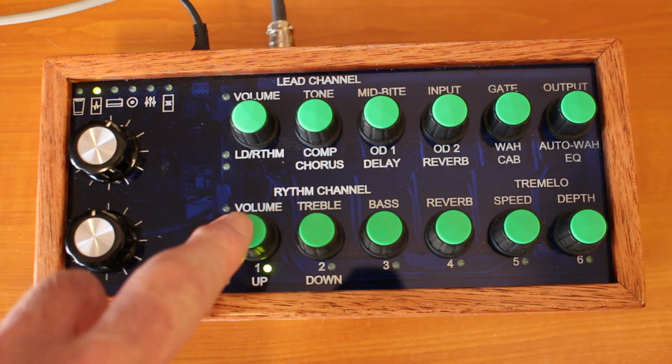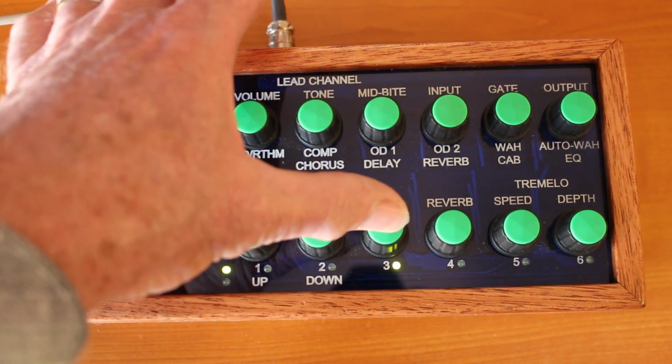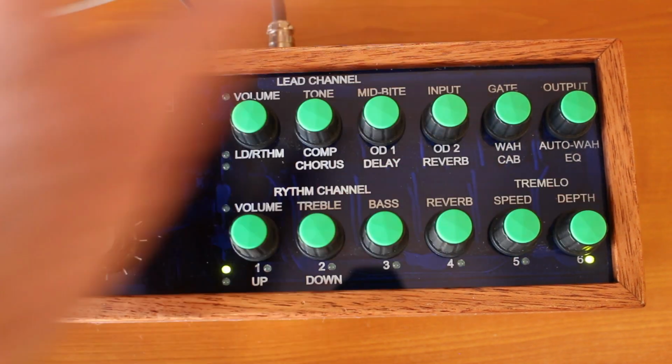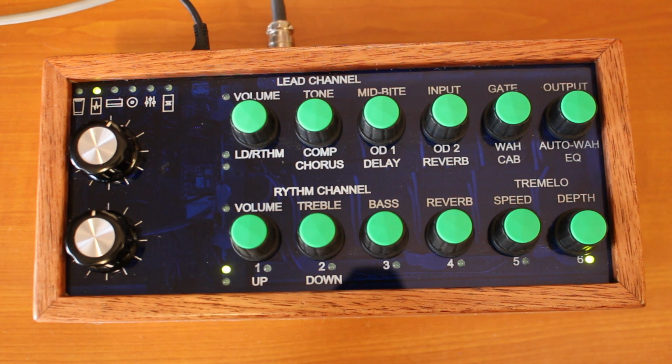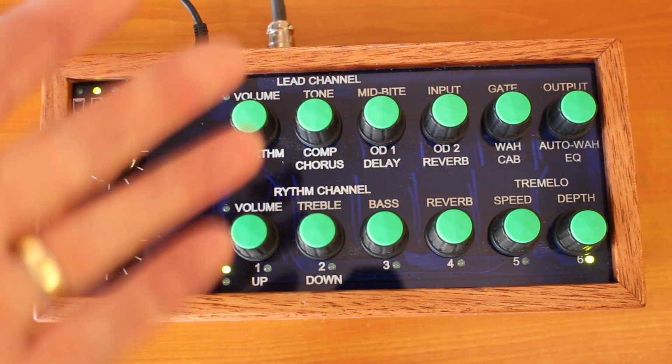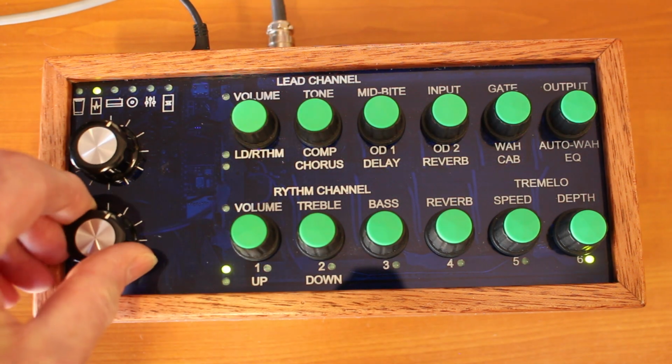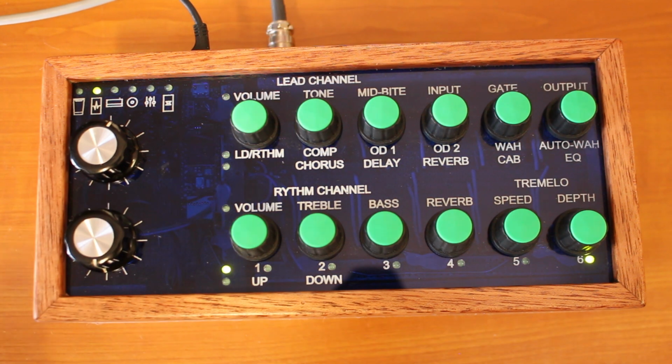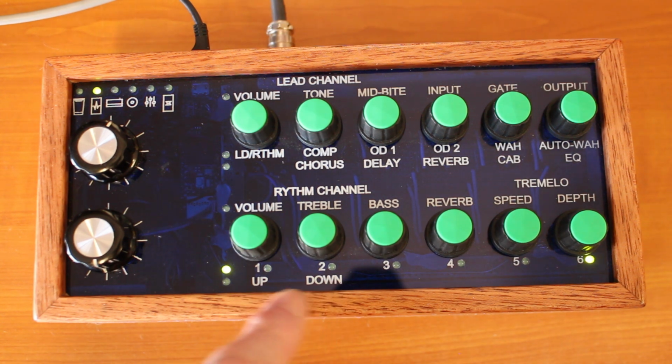The lower set of push buttons are all used to select different presets, and you can see there's an LED to indicate which one you've selected. So you've got six available presets. This rotary knob has 12 positions, and each position gives you a separate set of six presets. So altogether, with the 12 options, we can have up to 72 different presets. You can see that I've also got up-down labeling here. The plan is to allow for the possibility that two of the switches could be used simply for cycling up and down through either the banks of presets or the presets themselves. That isn't programmed in yet, but is a possibility for the future.